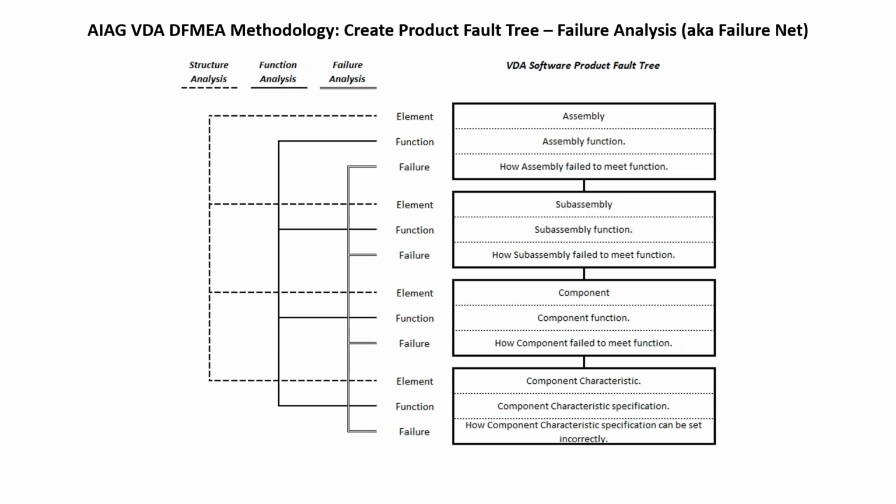He could take any failure in an assembly function and quickly drill down to what the characteristics were that were controlling it by basically traveling this path. Why he called it AIAG-VDA, I don't know, but the bottom line is people looked at this and they say, because one of the fundamental mistakes that people make about FMEAs is because of its name, like design FMEA, they think the job of the design FMEA is to identify all the failure modes. It's not. The job of the design FMEA is to assess the risk of releasing the hardware specs and software code if it exists for use.